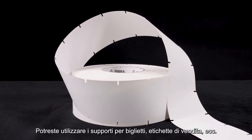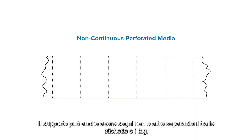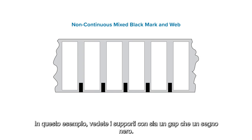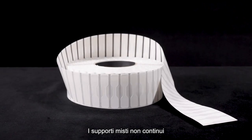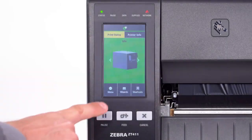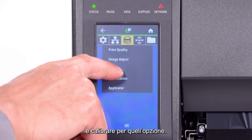Non-continuous perforated media has perforations that allow labels or tags to be separated from each other easily. You might use the media for tickets, sales tags, and so on. The media may also have black marks or other separations between labels or tags. Set your media sensor based on the type of separator used in addition to the perforation. In this example, you see the media with both a gap and a black mark. Mixed, non-continuous media will have more than one type of label separation indicator. You may choose which media sensing option works for your situation and calibrate for that option.